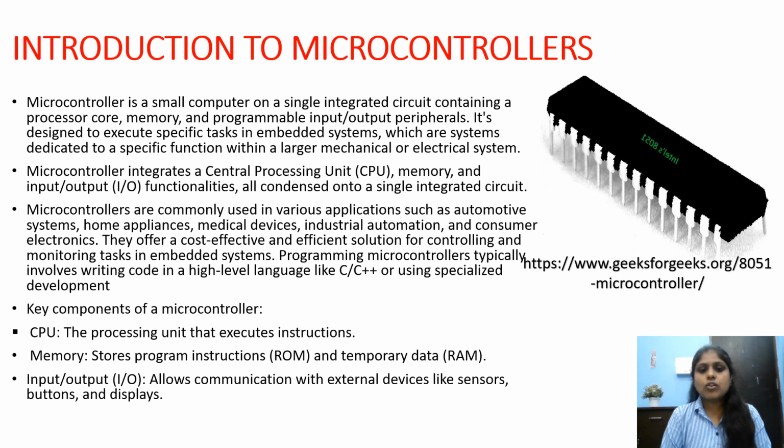The key components of a microcontroller: CPU, the processing unit that executes instructions; memory, which stores program instructions, that is ROM, and temporary data, that is RAM; and input output, which allows communication with external devices like sensors, buttons, and displays.